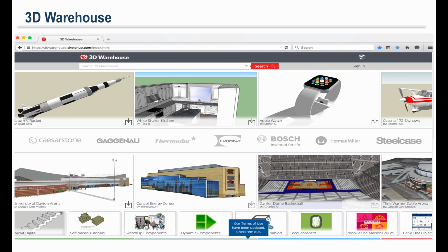Trimble SketchUp has the 3D warehouse as well, and this is a great place to locate manufacturers' content or use archival data you might have in SketchUp. You can easily import and export content here by using the download from 3D warehouse and the merge function in ARCHICAD. I usually recommend that you save them out again as ARCHICAD objects, and then this is a good place. You can also use the new favorites to organize all of your 3D SketchUp model pieces.